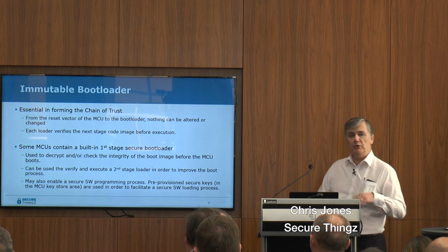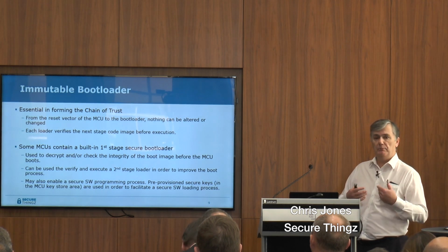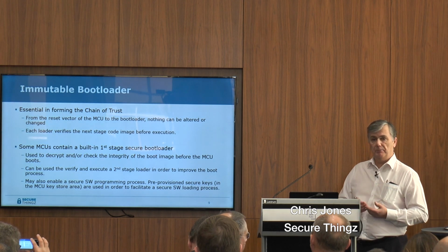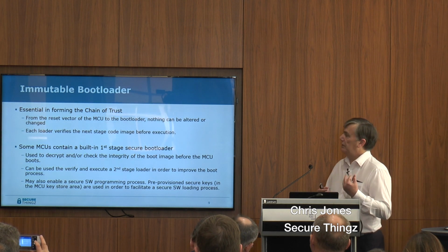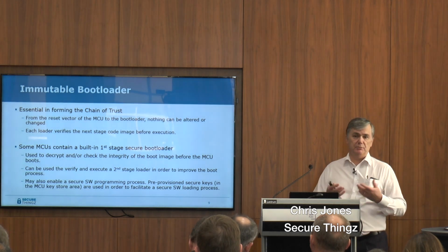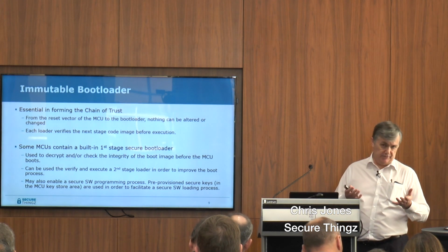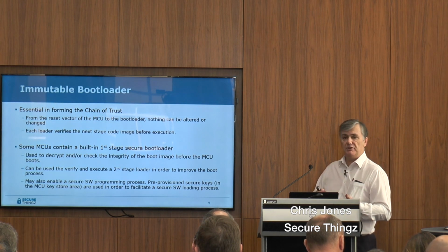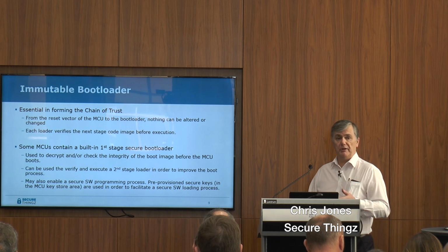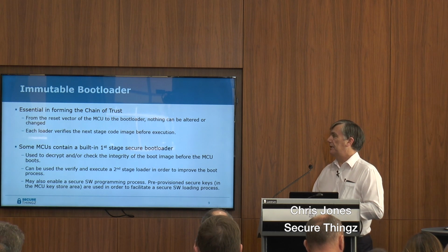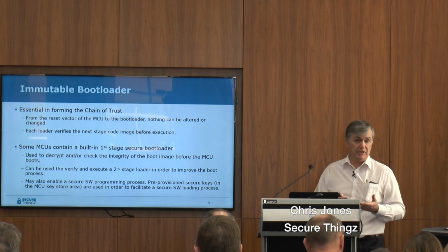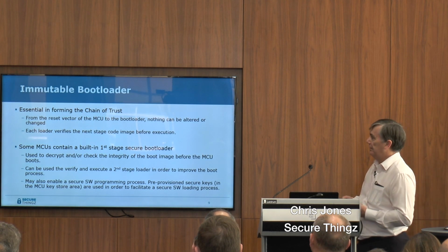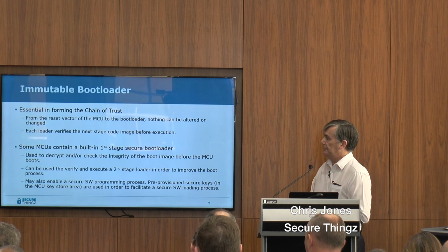So this is from your reset on the device, it boots up and it should jump to, ideally, as I said, a ROM bit of code that executes, maybe configures the device to boot up, checks, sets up the clocks, etc., to get it up and running in a stable state. And ideally, it then checks firmware that's on the product in the flash area, does some verifications, checks a hash or some signing of that bit of software before it actually jumps to it. So a very important part of the system.